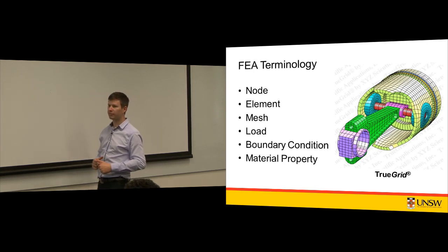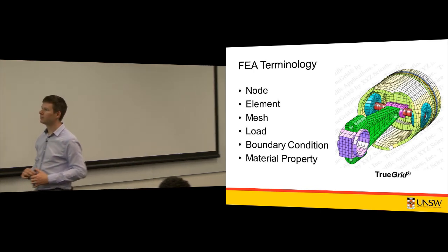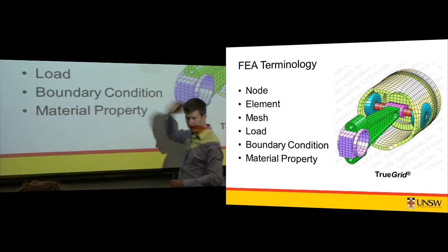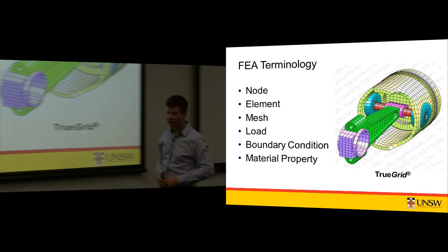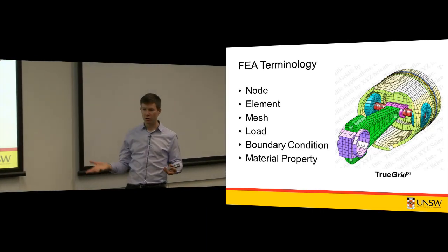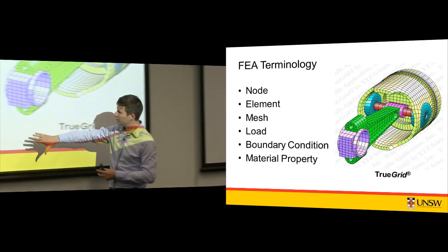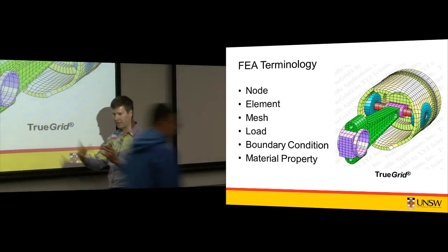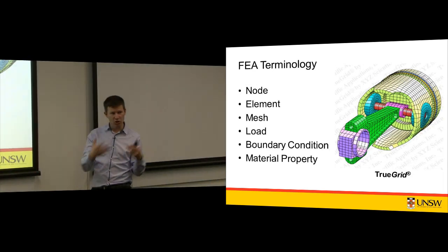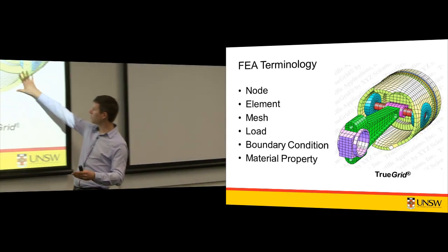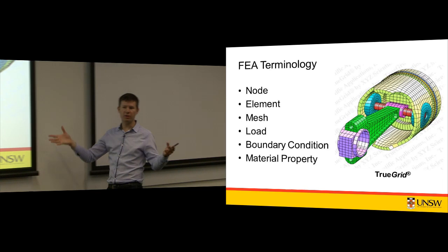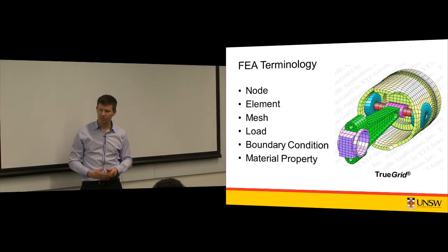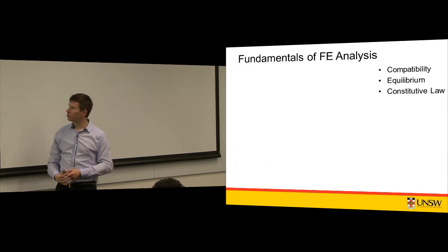Does geometry come under material property, or is that more about the actual material? No, so material property is independent of geometry. Absolutely, yep. So how does this material behave? Which is really good, because you can determine material properties in a standardized testing environment with a cylindrical bar under ASTM standards, and then you can use that material to make a complex geometry out of and generalize the material properties. It's quite a power and a strength of the method. Cool, good. All right.